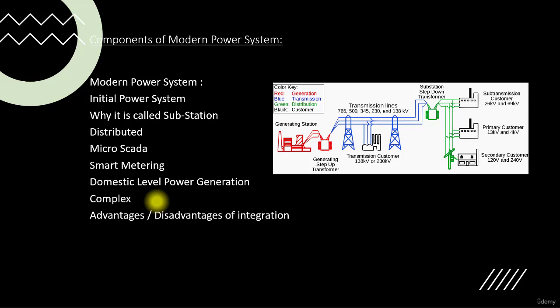to monitor and control. There are advantages and disadvantages of this integration, of connecting all the equipment together. The first disadvantage is that the total fault MVA is increasing, and another is that cascade tripping can shed the whole system if it's all connected together.